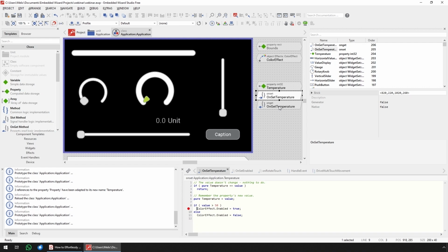It can be with just 3, 4, 5 API calls, a very lean one, or it can also be very big with asynchronous mode and with a very, very deep and detailed interface. Everything is possible. There's just one thing you have to keep in mind: Embedded Wizard can use any APIs, so maybe synchronous, asynchronous, push-pulling, message-based, whatsoever. But you need to first define the API according to your middleware, to your business logic, inside Embedded Wizard before using it, because there is no one.